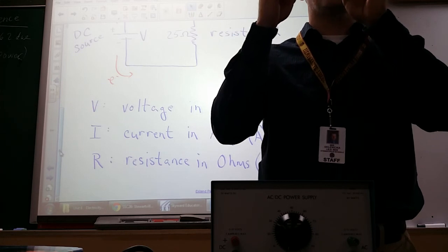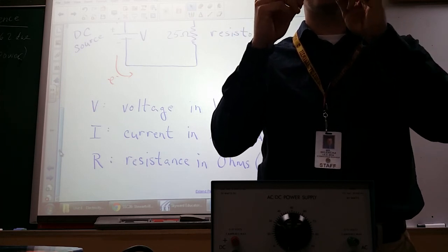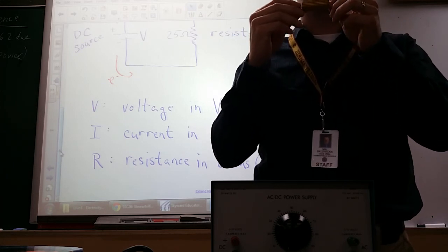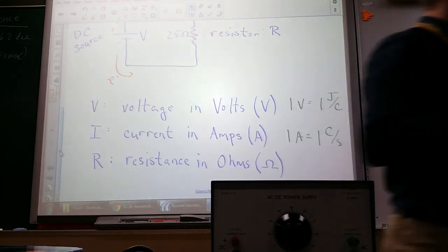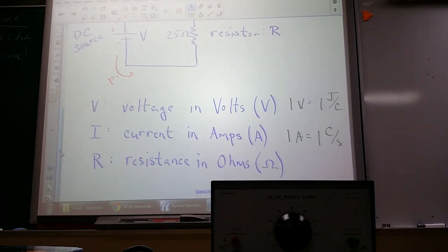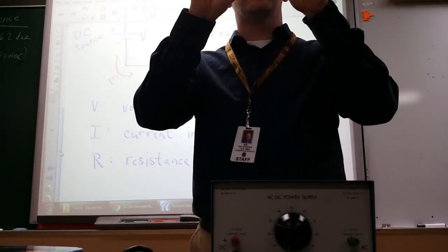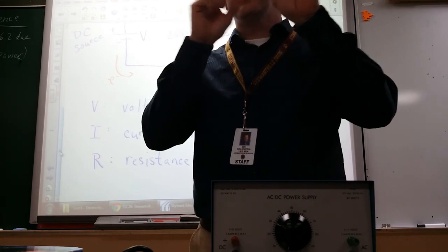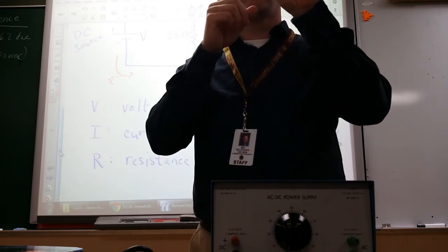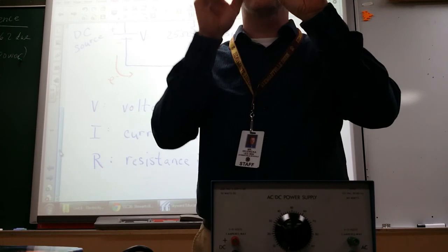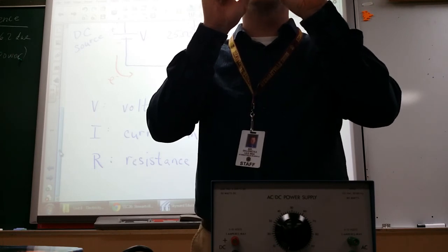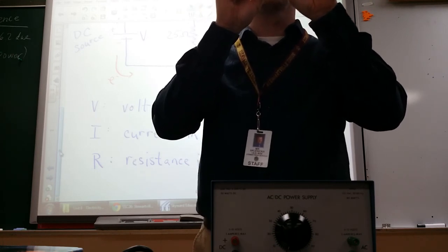Every resistor you can actually hold and potentially read. So this one's actually just typed. It says 12 ohms right on it. Other ones, they come in a lot smaller sizes. So here's another one. Still large by most of today's standards. There's no text on this, but there's a color-coded ring. So this looks like a brown, green, red, gold.